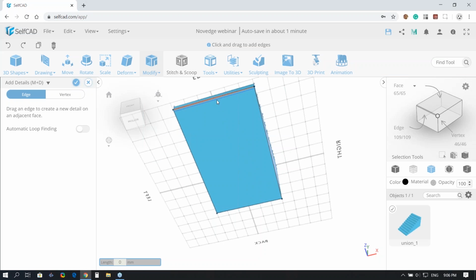There's a way you can just move it without dragging, but then it may jump. Sometimes it's not as good. Or you can just click on the edge and drag it. Then you can see it live update in the measurement box below. And also it gives you more control. But in this case, I'm typing in 50.